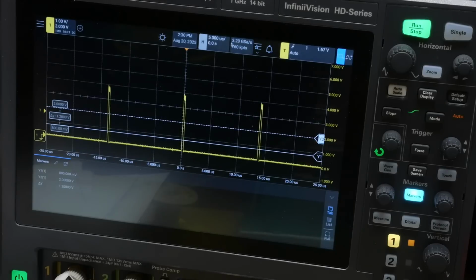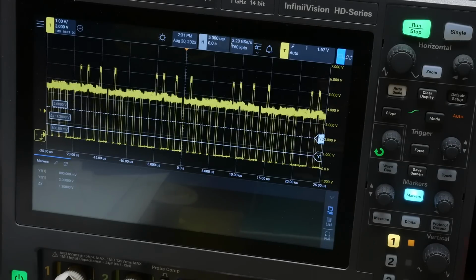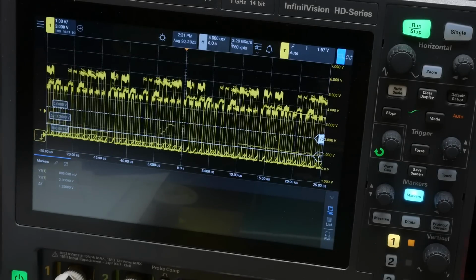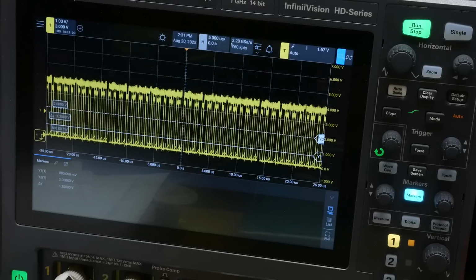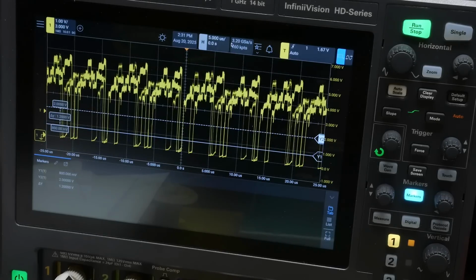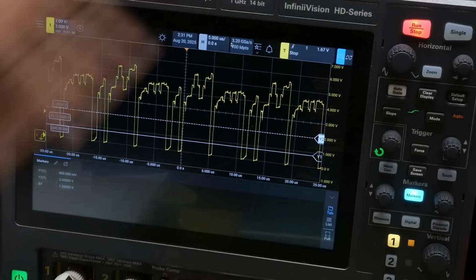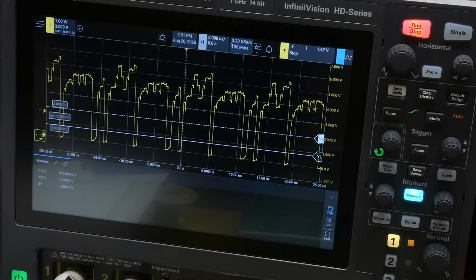All right. Some lines are gonna look pretty nice. They're not gonna look too bad at all. Some of them have kind of a different structure. So as you probe around an old TTL or old NMOS type system, look at this one. This one has 4 levels. Yeah, look at that. But they're all above 2 volts.